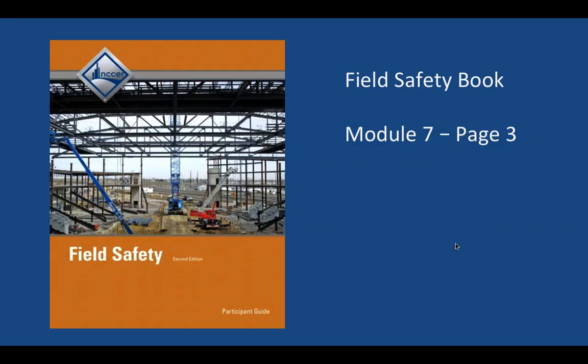That's why we often talk about, do we have the manual? Do we have the manual for a piece of heavy equipment? Do we have a manual for a crane? The biggest and most important thing is that it provides our inspection process. But the same goes for a scaffold, and the same goes for our fall protection as well. The manufacturer ultimately is going to be the one that determines what our scheduled maintenance and our repair maintenance is going to look like.